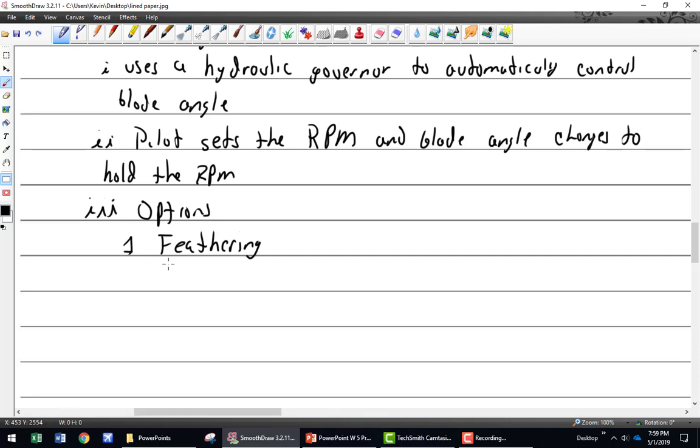So one data point, we always teach that a windmilling propeller produces as much drag as the rest of the plane. Really? That's a lot. The comparison was like a helicopter coming down in autorotation. How much drag that produces to produce a soft landing on a helicopter. Oh yeah, that's a good point. So in the small twin engines, if you don't feather the propeller, you're not going to go up.